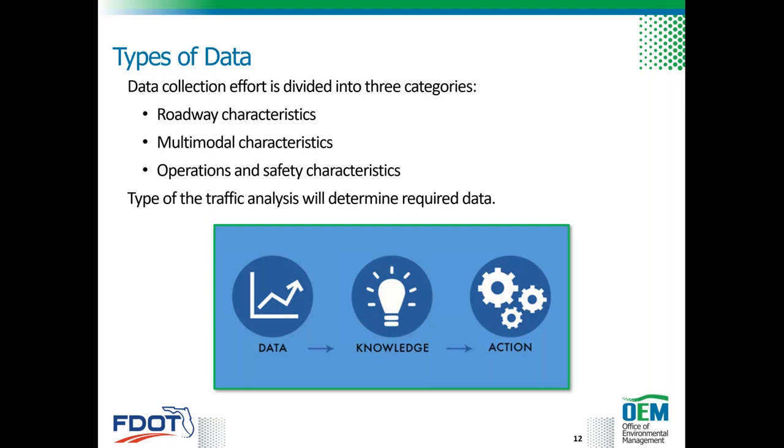To list some would be the posted speed, queue locations and lengths, number of crashes and locations, and the severity of crashes. And talking about crashes, the most typical length of crash data is a total of 5 years of crash data for the crash analysis.